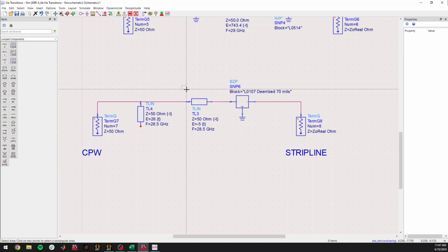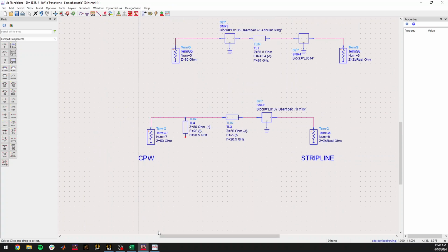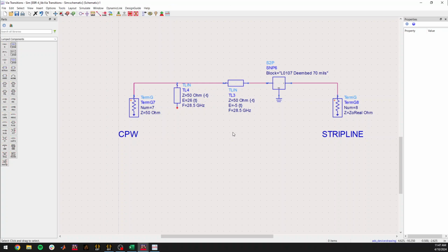So here's my S parameter file, and based off where I'm seeing this impedance on the admittance chart, I have two tuning knobs. I can change my electrical length from that transition, which is essentially like a pseudo de-embedding. In this case, you can make it negative to pull it further away, or add length to put it closer to the port. Additionally, I think I can realize this matching network with a shunt stub, or shunt open stub. So I'm going to gloss over the tweaking component of it.